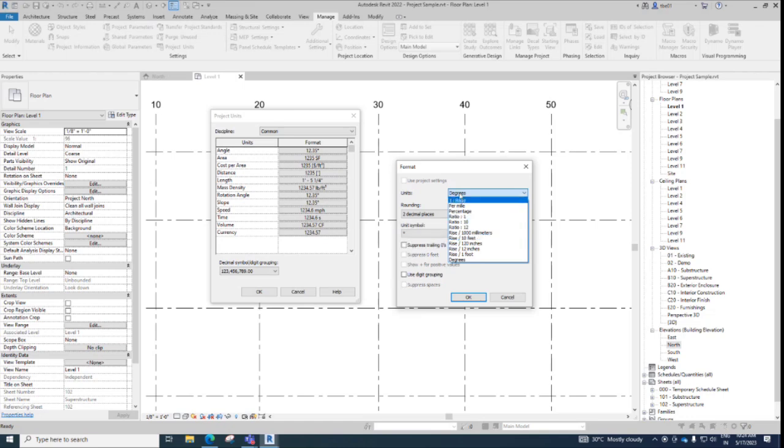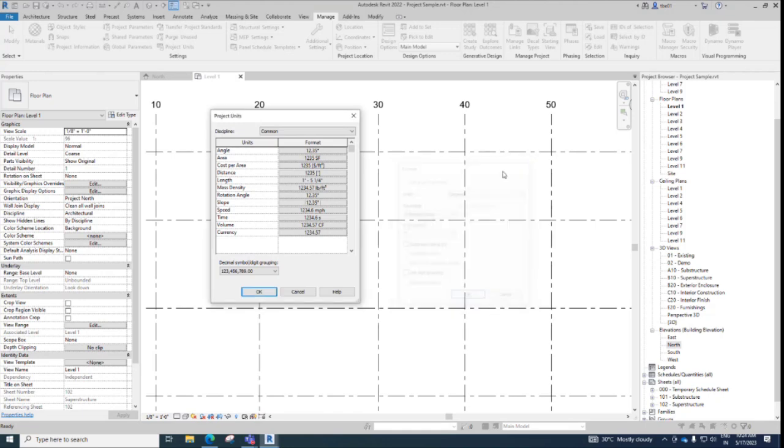All right. So degrees, it is kind of uncommon. But if you have a gable roof or a sloped roof, you can give the rise, like in this, 3 inches per 12 inches. So every 12 inches length, 3 inches will rise. So that's what it means. All right. So you can go through the other units, you can set it accordingly.